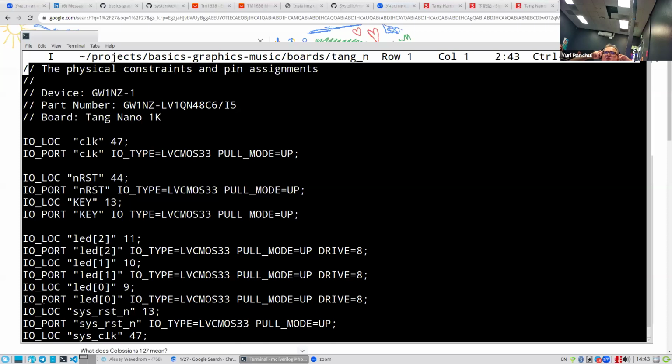By default, it's one when it's not connected, but it's connected, so probably you can remove this pull mode from here. Same thing about drive. What is an IO type? Different pins have IO types, but I don't know the physical meaning because I'm not the physical designer. So this is like a low voltage CMOS, 3.3 volt, something like that.